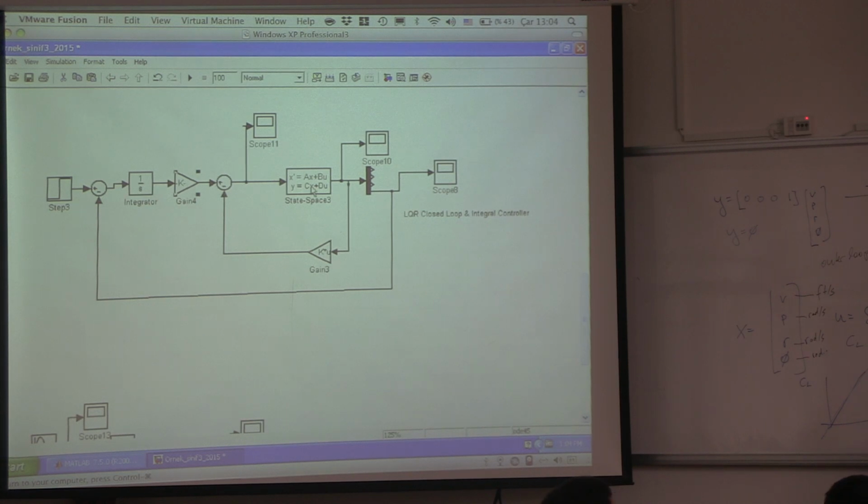Now, you might say, how are we going to calculate this feedback gain K, right, in conjunction with LQR? Because we never did that. We had just 4 eigenvalues, right? And then we added an eigenvalue for the integral. Remember that? How did we calculate the integral gain? I gave you 2 desired eigenvalues, or 3, whatever, and you added the 4th one, right? And that was supposed to be far away from everybody else. That's how you design the integral controller.